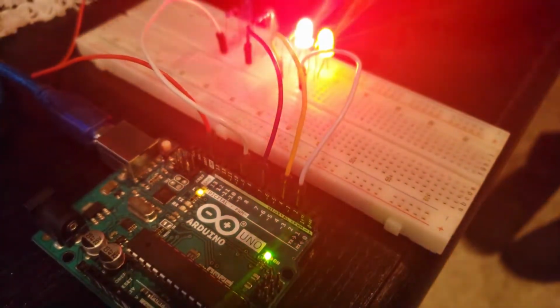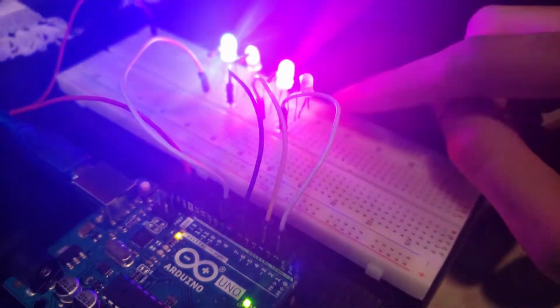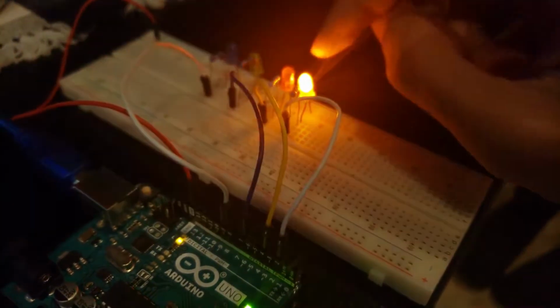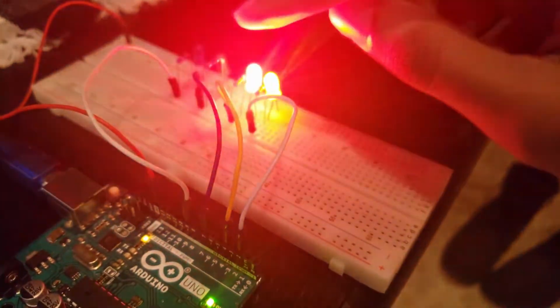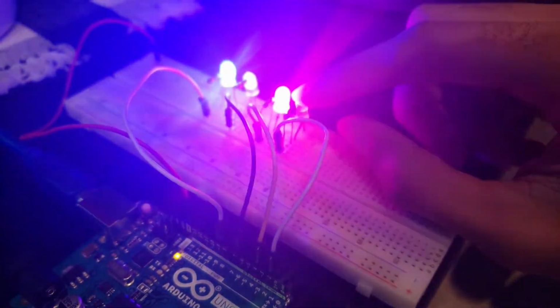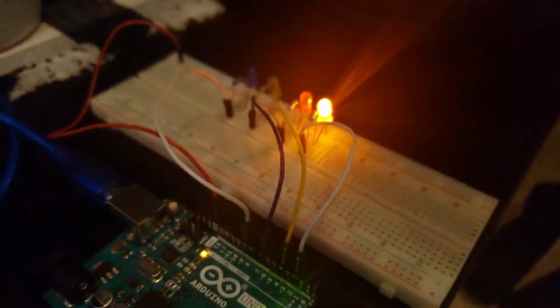So as I always do, I explain the whole electrical standpoint, the electrical schematics behind the scenes. So 5 volts flows out, goes through the resistors, drops down to about 1.9, goes through all of these, well, specifically it just goes to this one, and then it goes back to the ground. So it's all individually, but still it's the same concept for all of them. It flows, drops down the electricity, goes through the light, and the next thing you know, it just flows back to the ground, and then it completes the circuit and completes the code, and it continues to loop forever because you got that void loop, man.